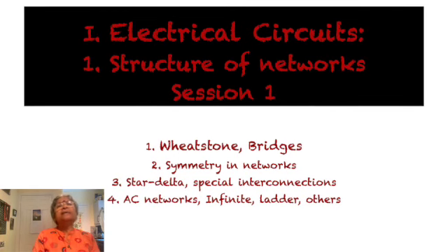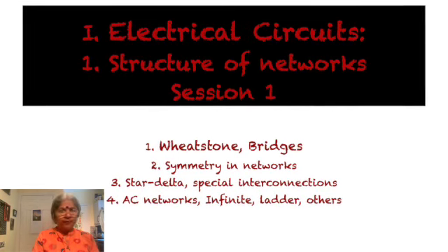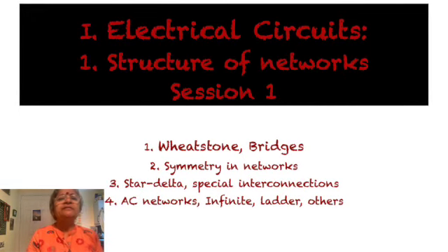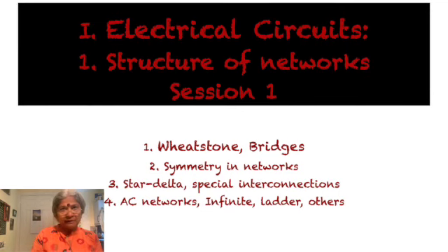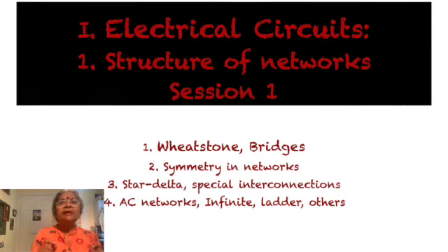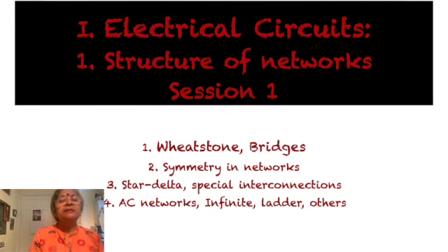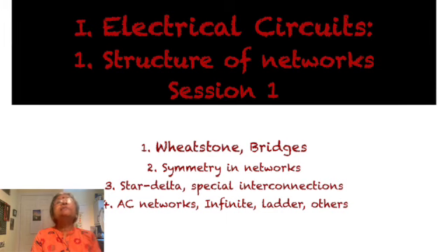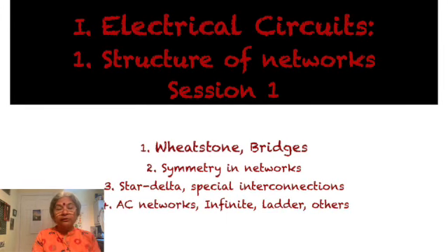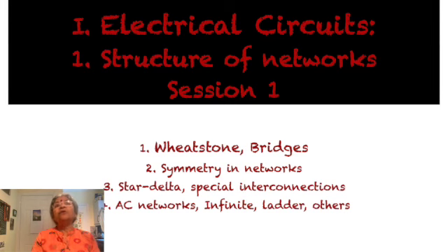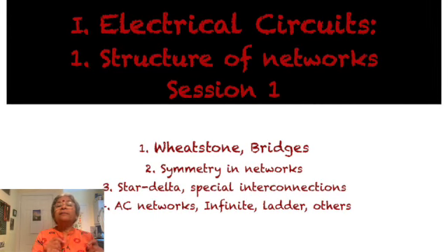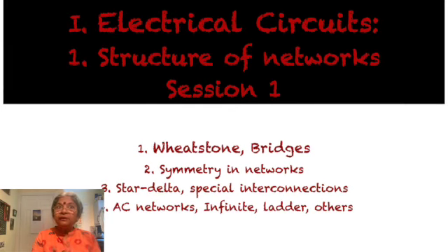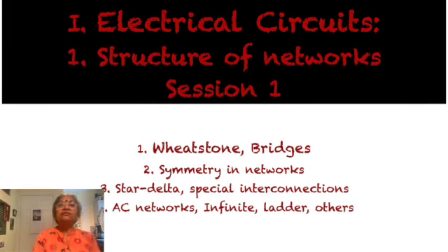Another important feature of Wheatstone bridges is that each bridge gives rise to a pair of terminals, or several terminals, wherein between these terminals no currents flow, whatever be the elements that you connect across them, which is equivalent to an open circuit. Similarly, currents do not flow because both the terminals are at the same potential, which means that if the terminals are at the same potential, this is equivalent to a short circuit.